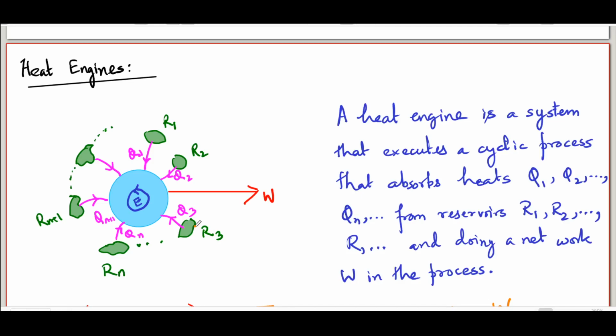The temperature of the body changes continuously during the process. What we are going to do is we are going to replace it by not a single reservoir, but a continuum of infinitely many reservoirs whose temperatures keep on changing from the desired initial temperature to the final temperature, keeping in mind the exact way in which the temperature of the body exchanging heat with our system had changed. So, we are really not saying that reservoirs are the only things that my engine exchanges heat with. However, replacing whatever the system exchanges heat with a series of reservoirs, maybe a finite number, but very often an infinite number, whose temperature varies continuously, will exactly give me the same basic results in thermodynamics, and using reservoirs will make the theory a lot easier for us to work with.